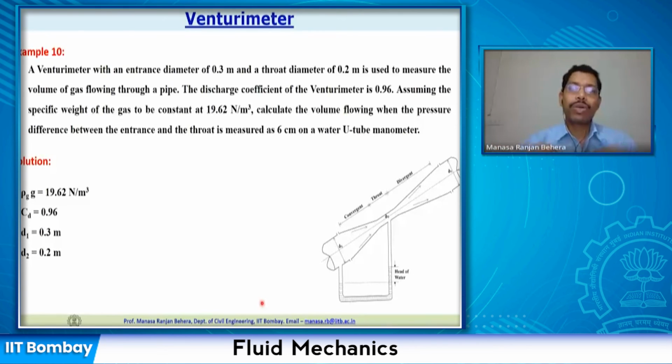Let us find out what will be the pressure at this location. If I draw a line, we know that in a continuous fluid, at 2 points that are at the same elevation, the pressure is going to be the same. By applying that concept, we can say that the pressure here and pressure here are going to be the same.